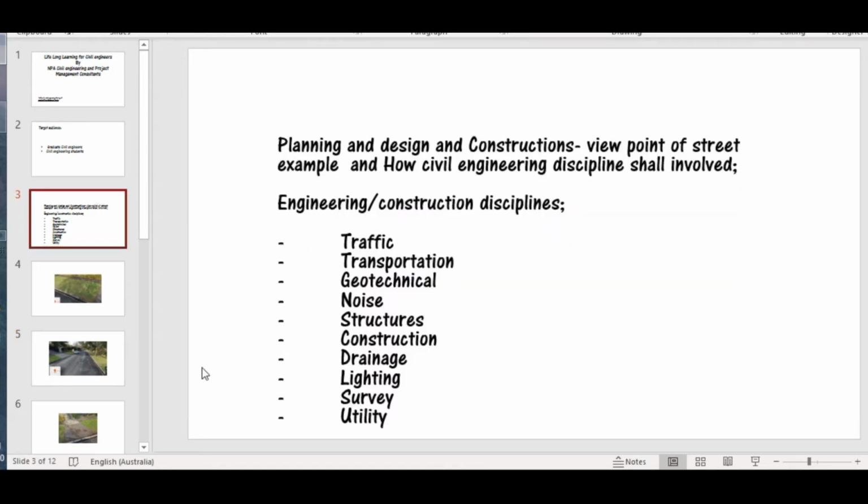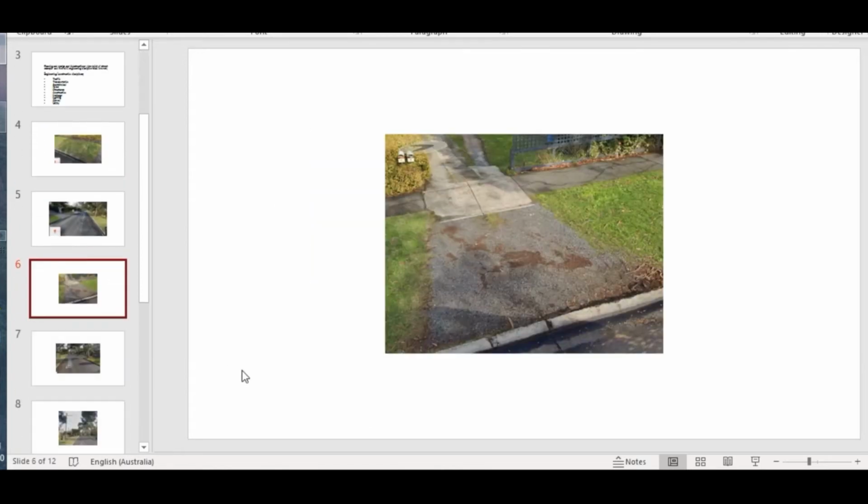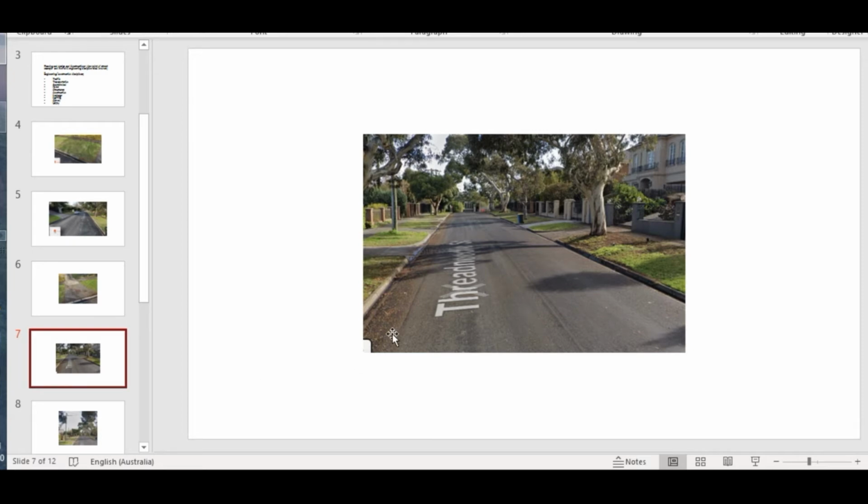So now going back to geotechnical, some of this different view of the road. For example, before we design or plan as a civil engineer, we might be involved in coordination as well as making sure that if that road is capable of carrying traffic, in terms of assessing the strength of the subgrade, as well as when we build up the road, assessing the road base strength of the subgrade, subbase, and base course.